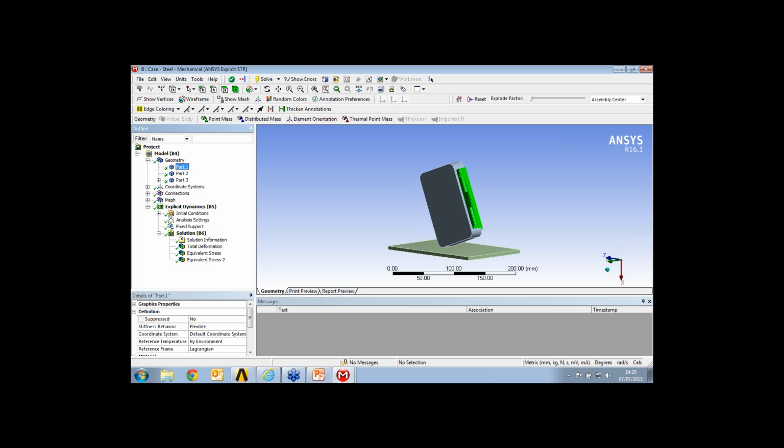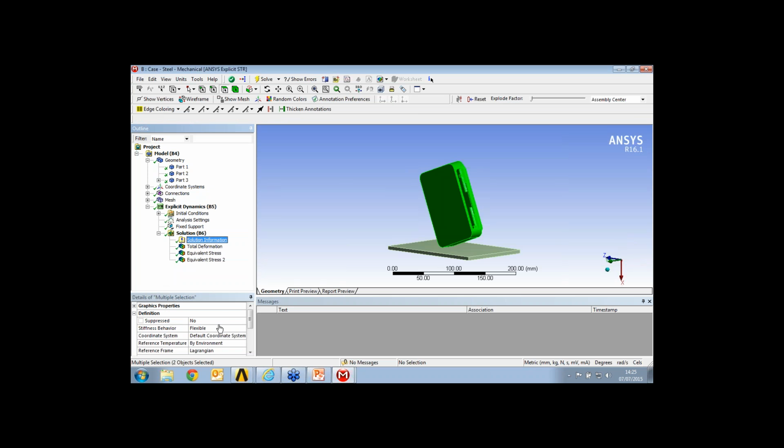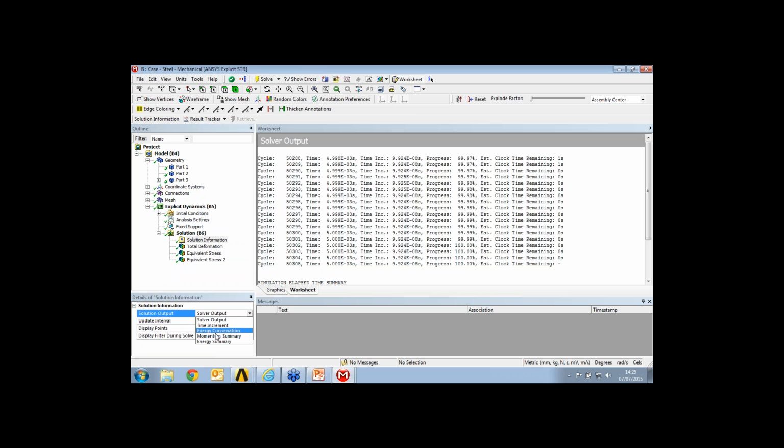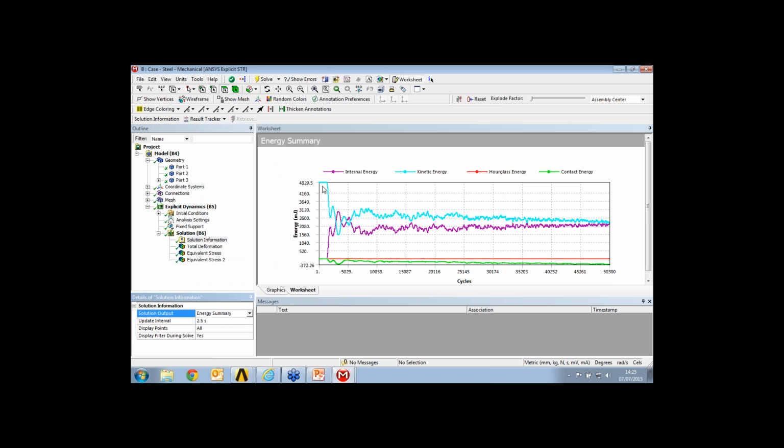So this is exactly the same setup. Difference being in this case is that we're using structural steel for the case rather than the ABS material. One thing we'll notice to start off with when we look at our results is the change in energy based on the amount of mass in the system. So moving up from 640 millijoules to a revised value of 4,830 millijoules. You can see also from the energy plot is that the 5 millisecond end time was excessive for this particular application.